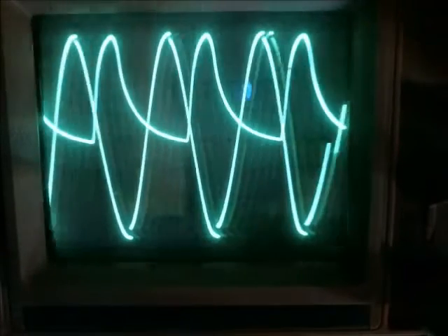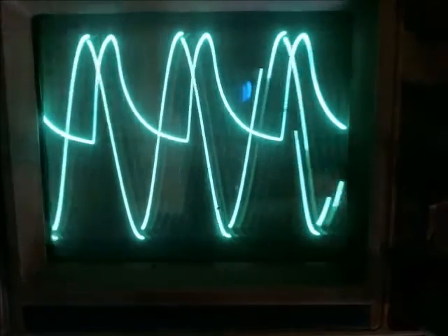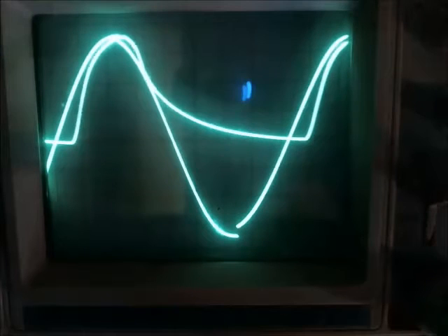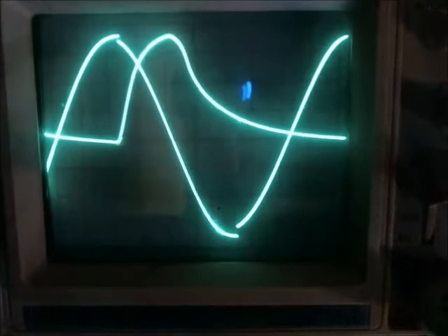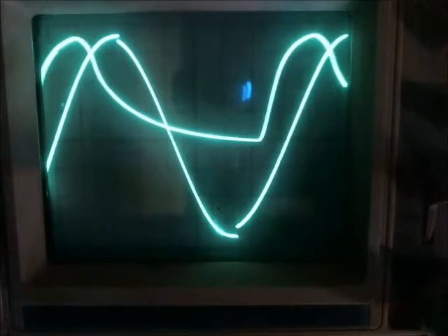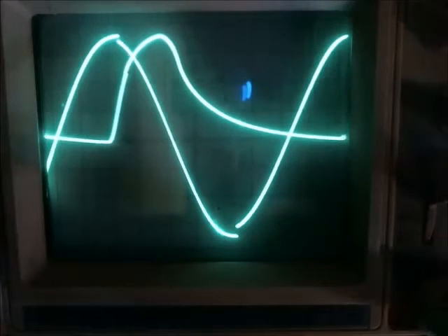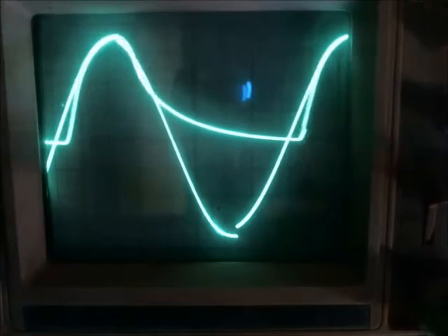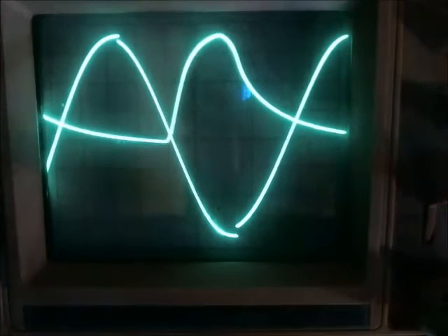If we overlay this with an AC waveform of the same frequency, you can see that when they overlap, only 50% of the energy is being put out as light, and the other 50% is really not being utilized. So let's see if we can improve the light output of the LED circuit.